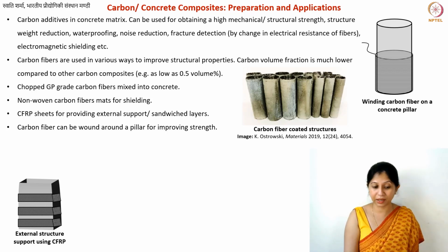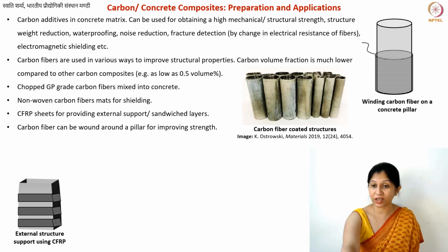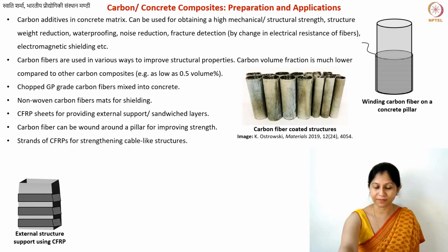derived carbon in this particular case, because you don't really want to go for mesophase pitch, because you don't much care for the modulus in this particular case. Tensile strength is more important, and turbostratic nature can also offer a little bit of strain hardening, so you may want to go for these kind of fibers.